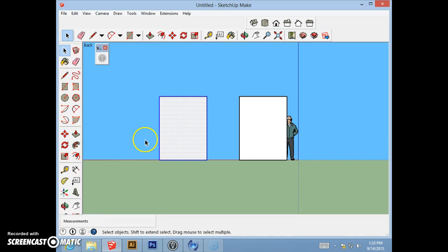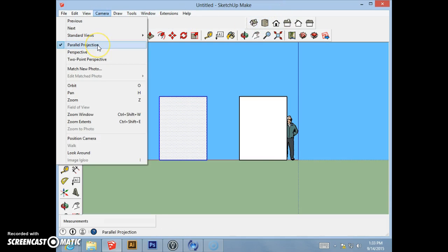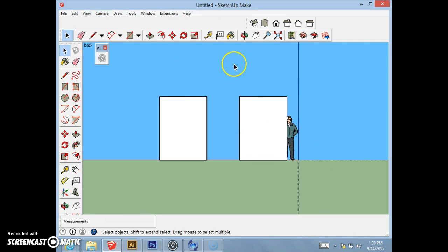But when you guys get started with this first project, it's intended for you just to get comfortable with this environment. This stuff that I'm showing you right here is some real basic stuff that can save you some headaches. You saw how easily I placed that form underground, below the ground basically. By using these techniques, setting your camera to a parallel projection and also using the move tool, it can be a lot less frustrating as you're trying to work with multiple objects.